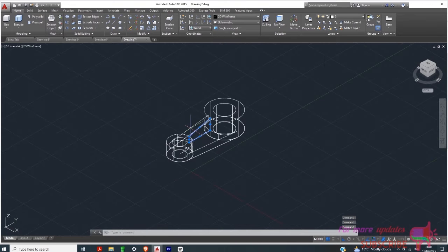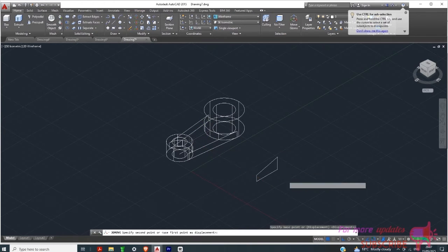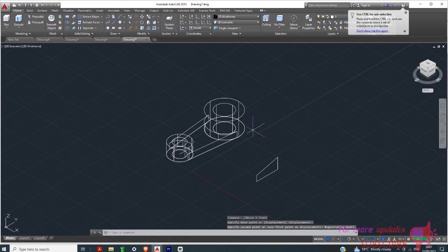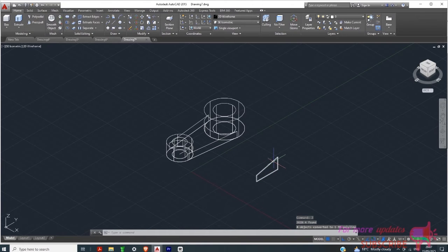And then this one I can just move, 3D move from that point. Okay, I will select everything here and type J and then join. Okay, it has been joined, and then press pull again from that. Okay, I want only that, again 12, enter.